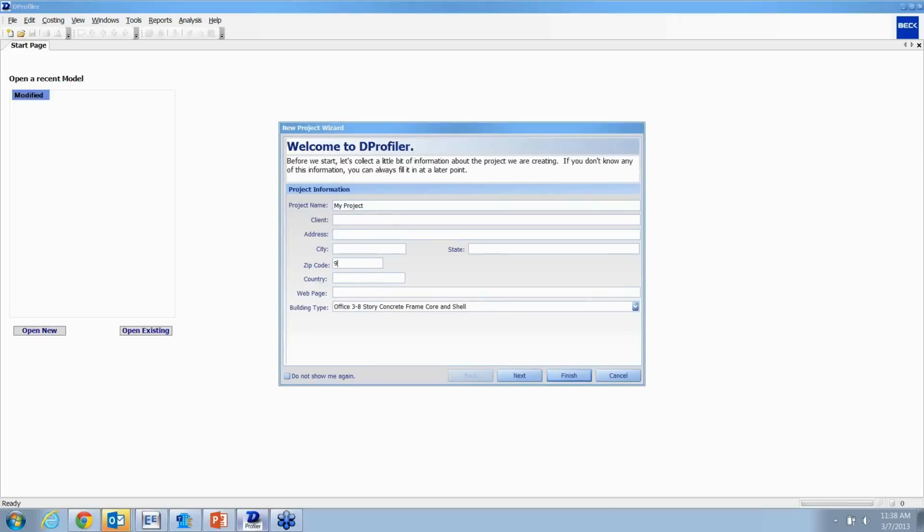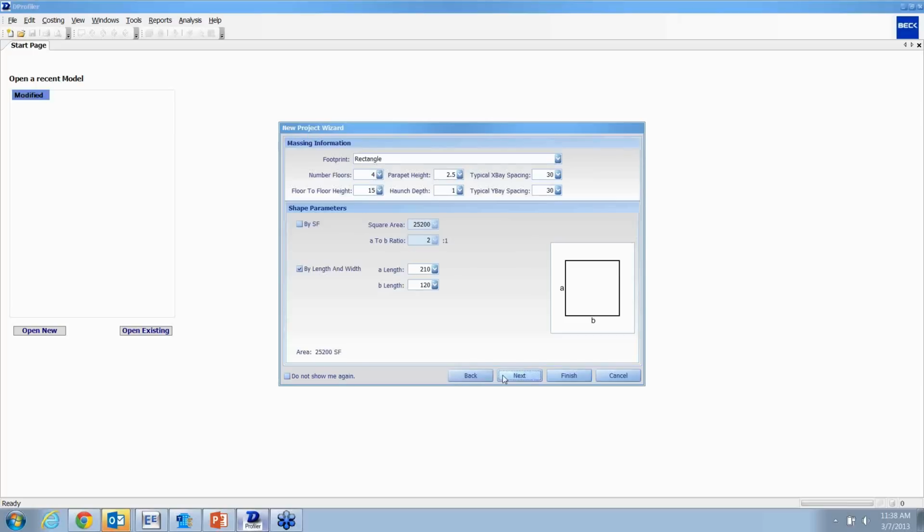If I utilize a zip code, it'll tie another avenue of running an energy analysis with it. You'll notice here on the drop down, this is the same concept of going to the Timberline cost model and picking out a multi-use questionnaire or a small box retail or a parking structure. And as I do that, I hit next, and here's some questions.